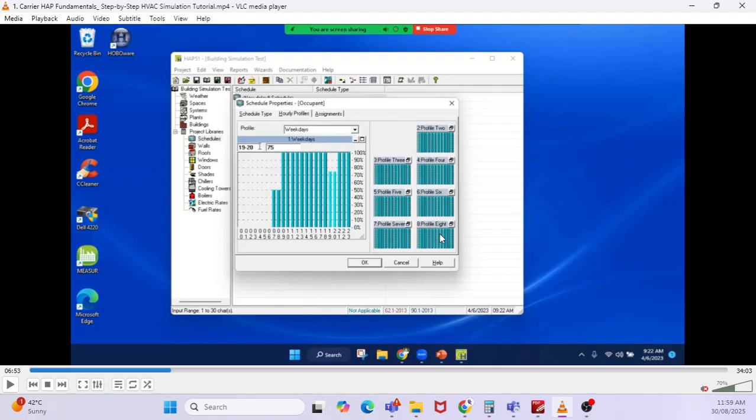So when you design your air conditioning load, you don't need to design for 100 percentage. Say for example, when you calculate for 100 percentage, you may get a 10 kilowatt machine, for example, right? But when you fine tune in this way, maybe you need only an 8 kilowatt or 7 kilowatt machine instead of 10 kilowatt. So you are saving 3 kilowatt, right?